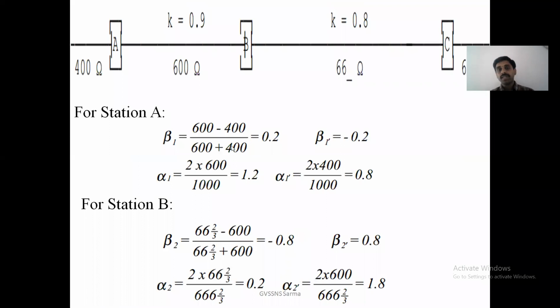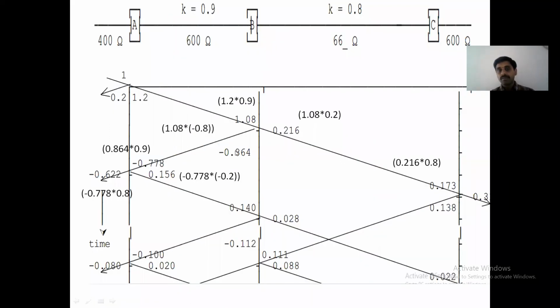Okay, so it is multiplied with minus 0.8, and the value coming from here is some value, minus 0.864. That is multiplied with 0.9 attenuation. Then minus 0.778 is the value reaching here. At this position again, it is transmitted and it is again reflected. What is transmitted? Minus 0.778 into, we know this transmission coefficient 0.8. So that is minus 0.662, the value coming here.